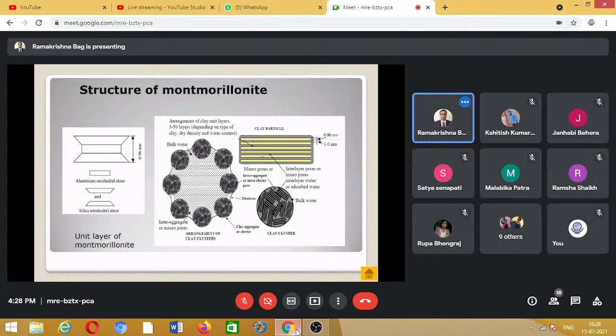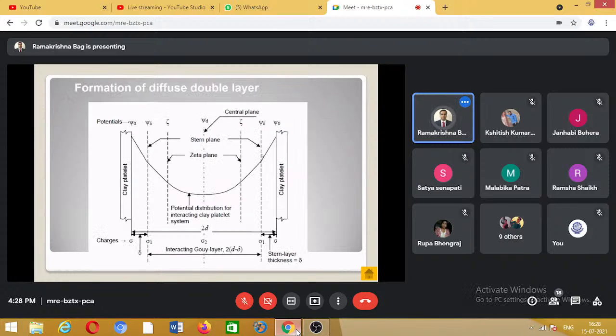And because of that, if water is trying to enter and you do not allow it to enter, what will happen? It will try to expand and push back. So some kind of pressure will be generated. That is called the swelling pressure. Because of this nature, it develops a lot of swelling pressure. So as engineers, we need to find out the optimum value of this swelling pressure. We cannot allow it to expand as much as possible, as then it can even break the canister. So you can study the montmorillonite structure and how these things take place. That will give you a much better idea.